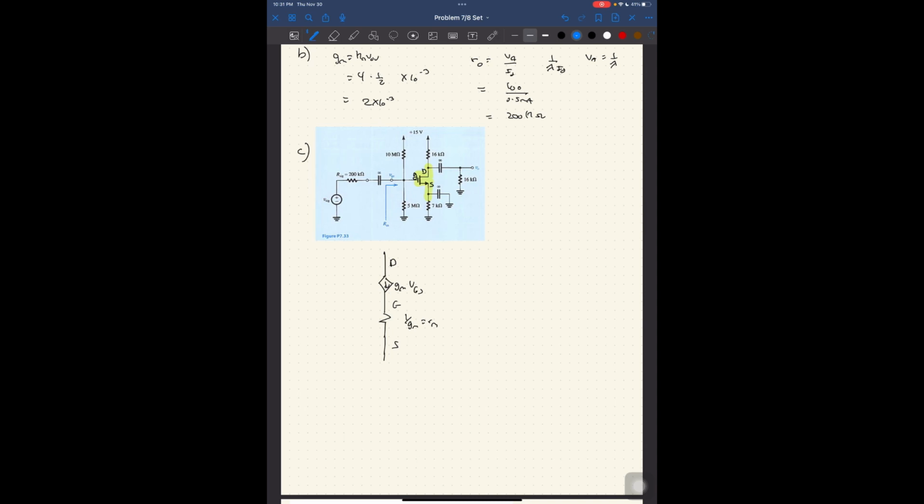The first thing that you have to understand is that there are no DC sources in the small signal model. You have to know this by now. There are no DC sources in the small signal model. Right, so this is 0 and this is 0. And step 2, capacitors are short circuits in the small signal model. Now, I can from the get-go say that, let's look at this part here. If I have a resistor and I have something that's short circuit, then this resistor doesn't count, right? So this is just a short circuit. So I can do this.